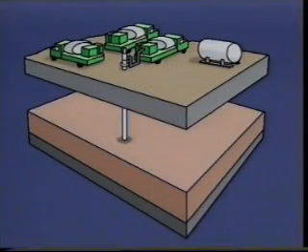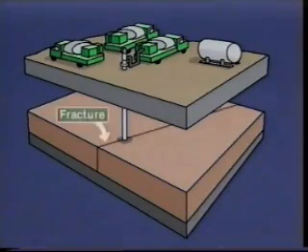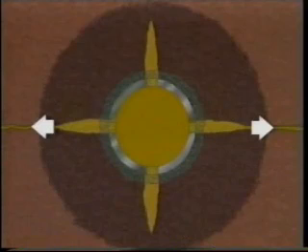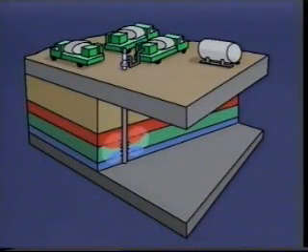Treating below the fracture pressure is especially important. If the formation is fractured during the treatment, acid will be diverted into the fracture and bypass the damage. Once the well is in production, the fracture could quickly become blocked with the damage, and the acid treatment will have been a failure. Additionally, fracturing during a matrix acid treatment can establish harmful communication with adjoining water or gas zones.